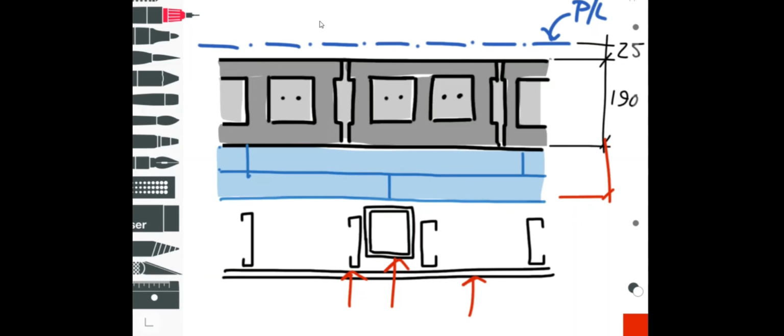And the beauty of this is, again, you don't know what's happening inside that space necessarily. So this wall could get beat up pretty bad, and no one's punching holes through your building envelope. Essentially, it's just a furring wall on the inside, and probably, oops, I erased my tape on there, but you basically have a pretty safe building envelope, I suppose. Now, there's going to be challenges for the detail where this wall meets your conventional wall with the outside insulation on the 2 ends or whatever, but that's just a detail that has to be worked out.